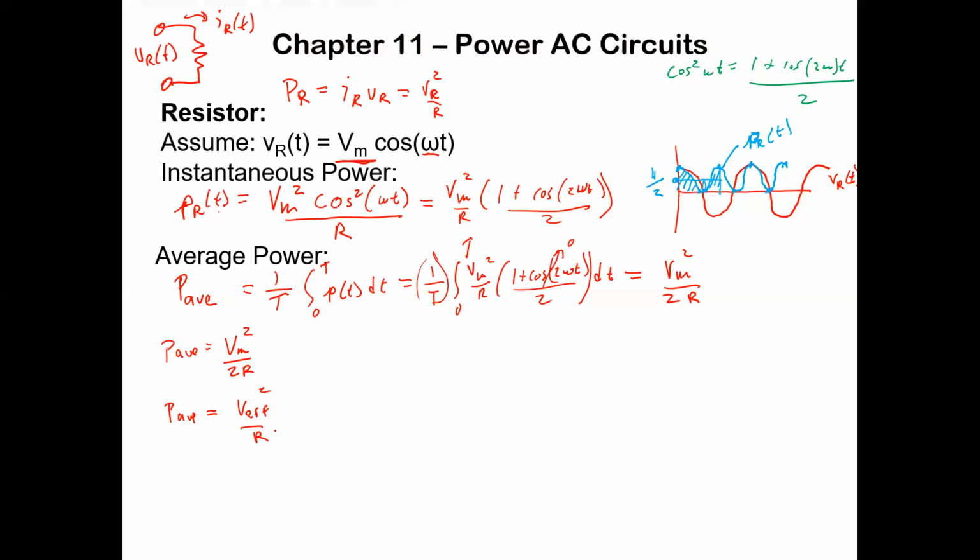So right, AC power is if you've got an AC sine wave with a magnitude of Vm, then you square it and divide by 2R, that's the average power. But DC power would just be V squared over R. So if you think about average power in terms of, well, what's that? You've got a sinusoid of magnitude Vm, and the power is Vm squared over 2R. Well, what would be the effective power if you thought of that as like a DC voltage?